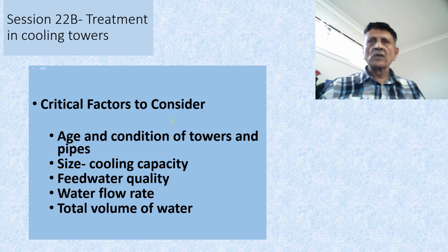Then the next is the water flow. The greater the water flow, the faster the heat can be transferred from the heat exchanger. We have to get it optimum because there's only a certain amount of water that can flow through, so that we have to use as little water as possible, but at the same time we want to maximize our transfer of heat.